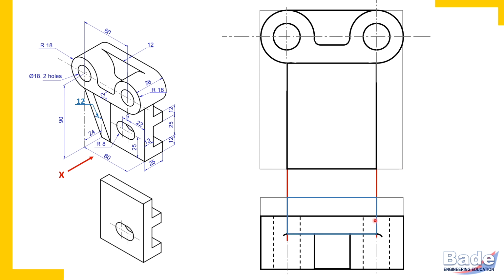Now this is very important to understand. Check carefully what I am telling you. Front view of the lower portion of the object: length 60, height 72. This is the front view. And the front view of the upper portion, there is no overlap here. But in this case, the top view of the upper portion and the top view of that lower portion, there is a certain overlap. The box, this F-shaped portion we are drawing here, is under the upper portion, and the portion which is overlapping, that is hidden. So when you complete this rectangle, you will have to take care of that. So watch here, this portion we have drawn visible, which is not overlapping, and this portion is hidden.